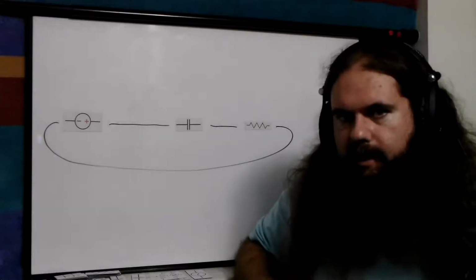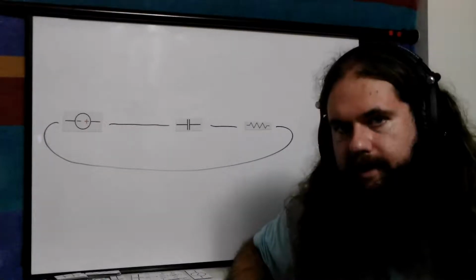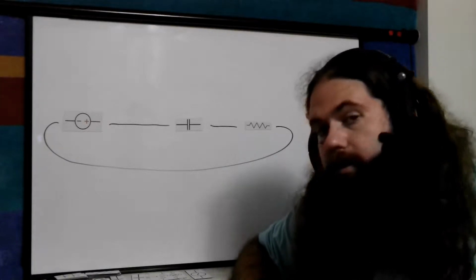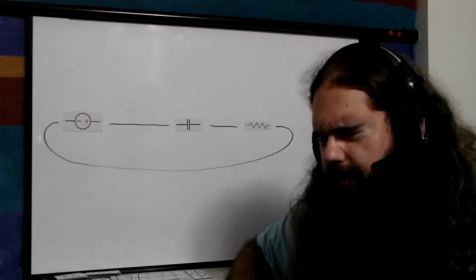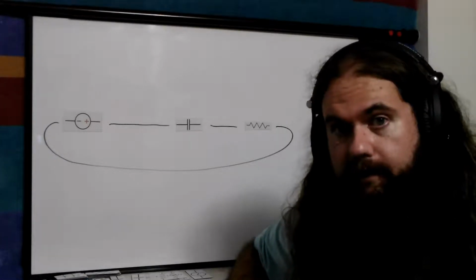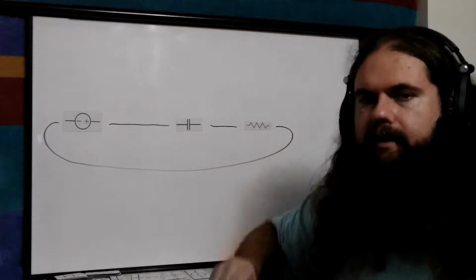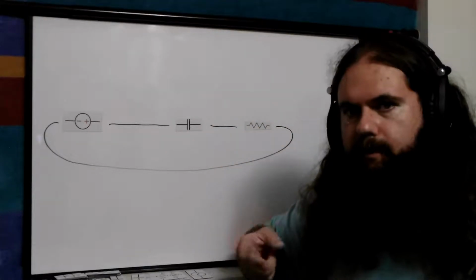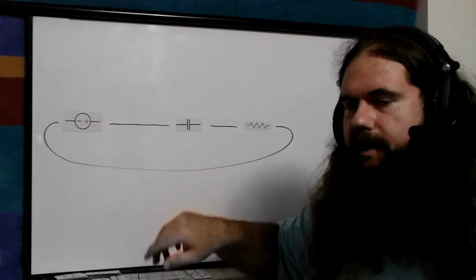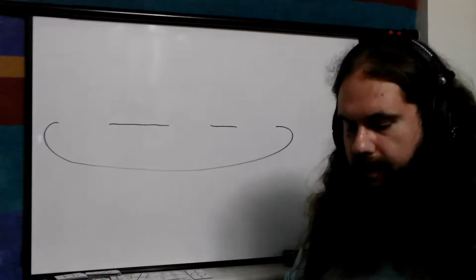That's why you see capacitors in parallel almost always. There are reasons to have capacitors in series. There are reasons to use capacitors in alternating current. But pretty much I'm not going to worry about that until some random point in the future where I need it. For right now, capacitors are a thing you connect in parallel to decouple, to smooth, to whatever, and we'll go into good examples of how that works in another video. For now, I'm simply going to demonstrate capacitors.